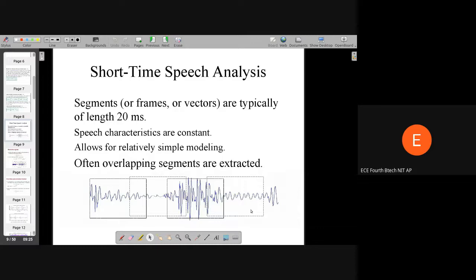Suppose now you took a chunk of that. You don't have the infinite sinusoid; you took a chunk of it. What will happen to the Fourier spectrum then? Well, then we'll observe something called windowing. But still, you will find that there is a peak at that omega naught in the frequency spectrum. That peak is now not an impulse; it is kind of dome shaped. So around that peak, there are also small values, but you can still see that peak at omega naught.